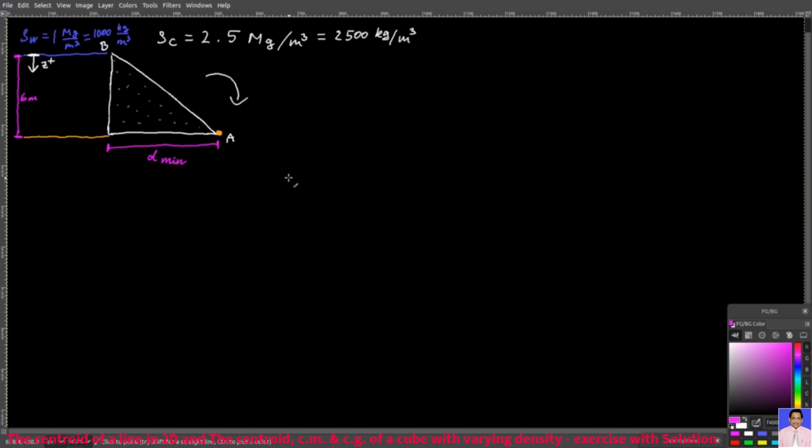So here's the thing about fluid pressure. You mainly have two types of fluids: liquids and gases. Liquids are assumed to be incompressible fluids. It means that the density of a liquid does not change significantly with pressure. So for example, here you have less pressure than here, but the density of water will be 1,000 kilograms per cubic meter in both places. In reality, nothing is 100% incompressible. But when it's very small, then you can still assume that.